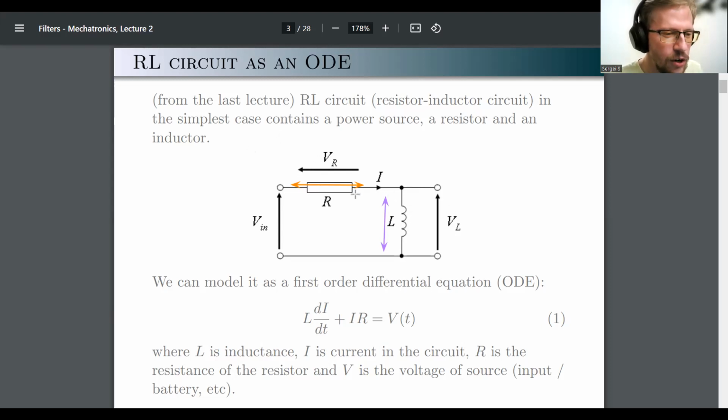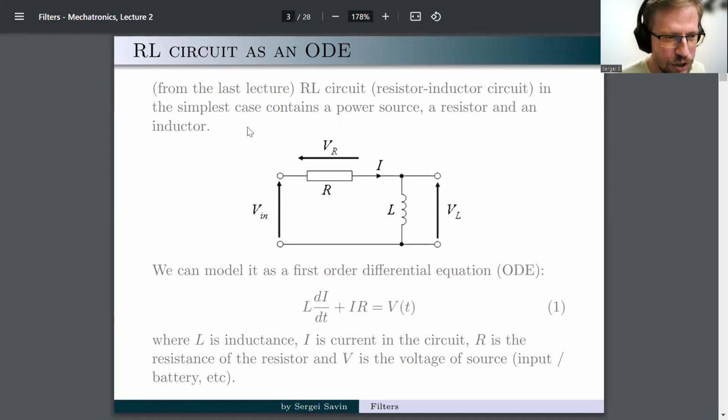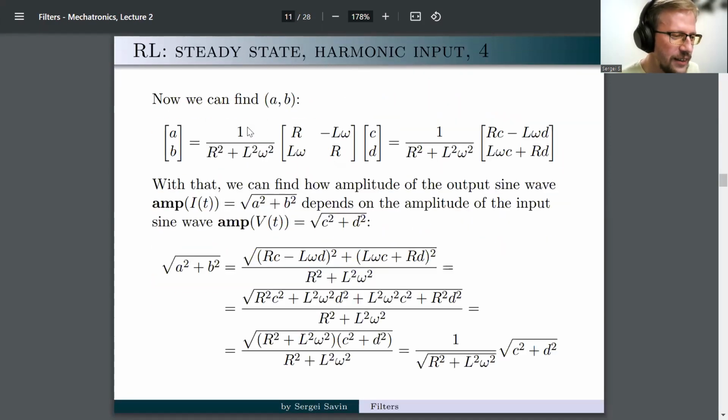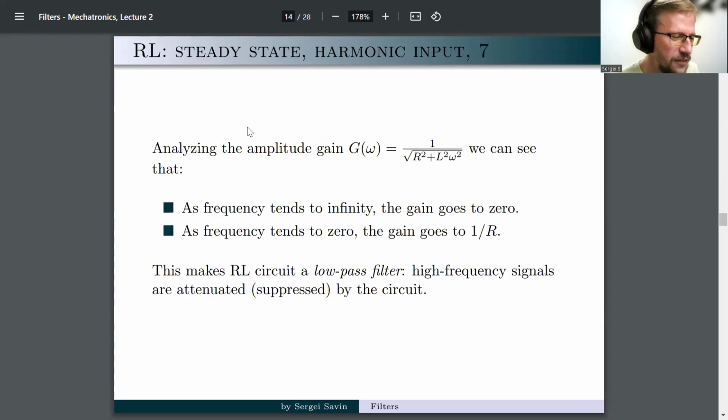So they are somehow antagonistic in this sense. And you can use the same circuit to achieve both behaviors. It depends on where you measure. That's what we call a voltage divider, because the sum of those two voltages is always equal to the input. Okay, that's just one comment that I wanted to make. It's quite a simple notion, but you have to hear it. Okay, now what we have here is what we call a low pass filter. Again, we are talking about current.